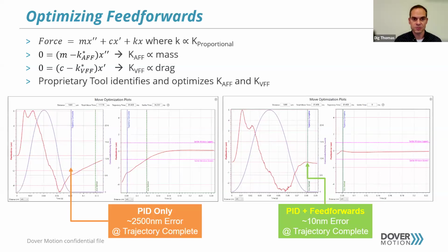And you're not worried about cranking your integral up just to get the thing to pull into position. So let the velocity and acceleration feed forward do as much of the work for you as you can, and save the variable work for the PID. So how do you do that?